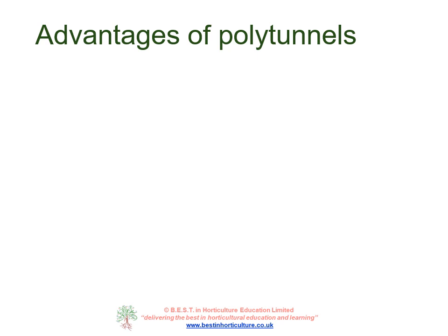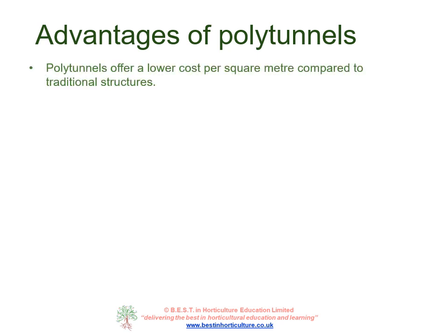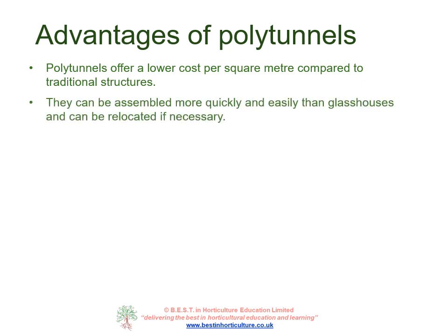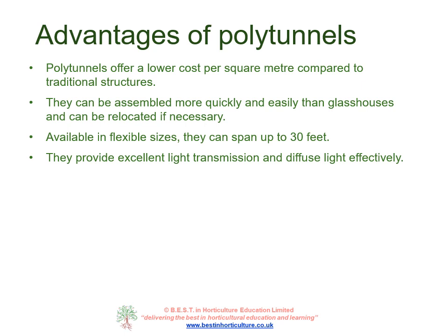Polytunnels have many advantages, including that they offer a lower cost per square metre compared to traditional structures such as glasshouses. They can be assembled more quickly and easily than glasshouses and can be relocated if necessary. They're available in flexible sizes and can span up to 30 feet or multiples of this. They provide excellent light transmission and diffuse light effectively.